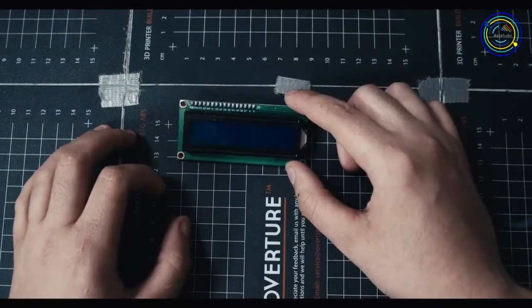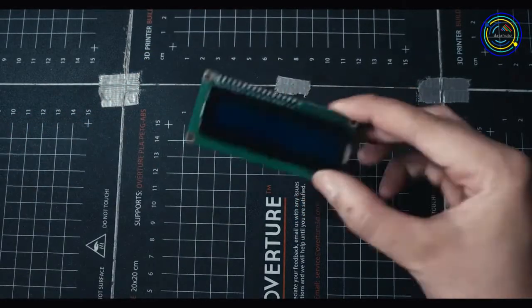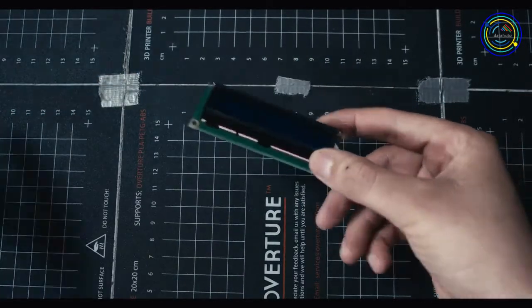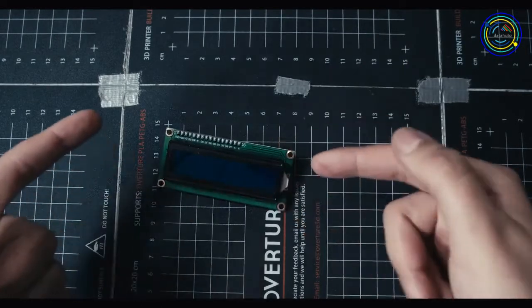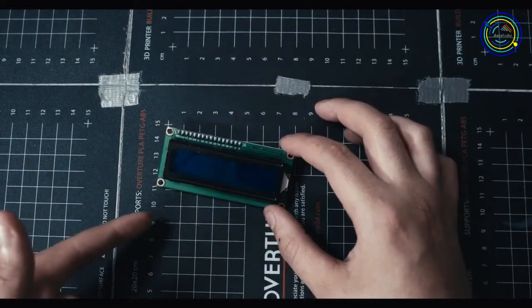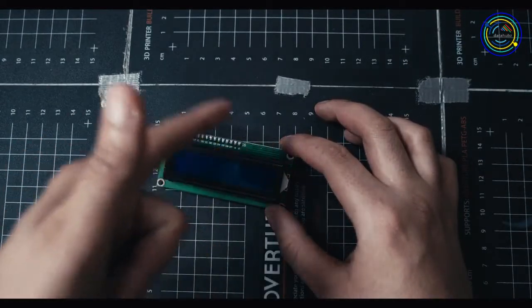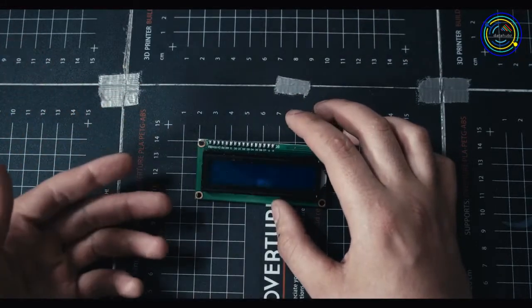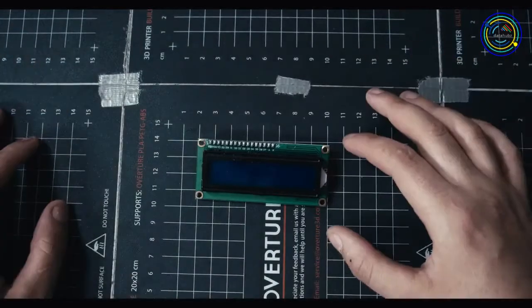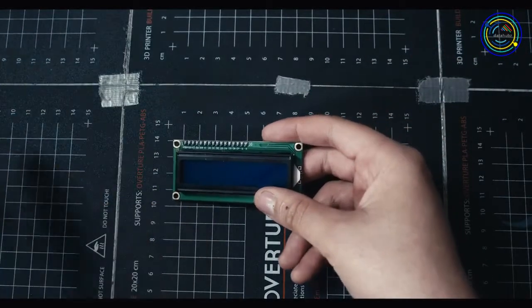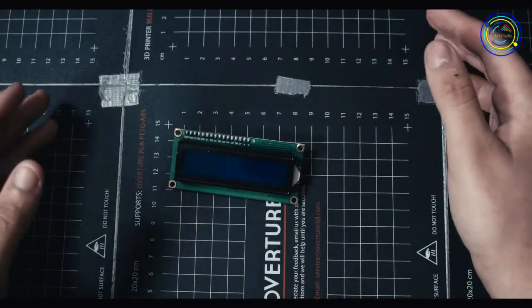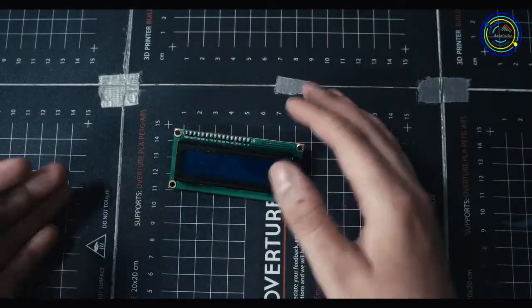This is definitely the one I would recommend everyone use. The price difference between one of these and a dot matrix or something like that isn't that big of a difference, so I'd always say go for one of these. You can get bigger ones. This one is 16 by 2, so that lets you put 16 characters in the top row, 16 in the bottom row. You can get a 20 by 4, or even a more complex one. These are a little bit more complicated than an LED matrix like this one, but just like our actual computer screens, they work in a simple manner but at a complex level.